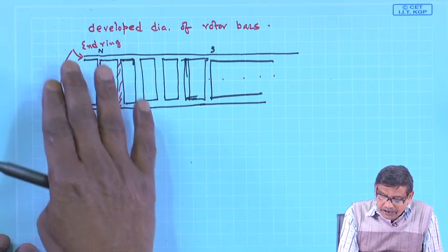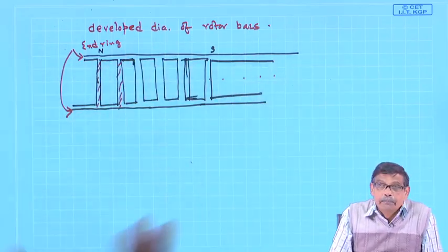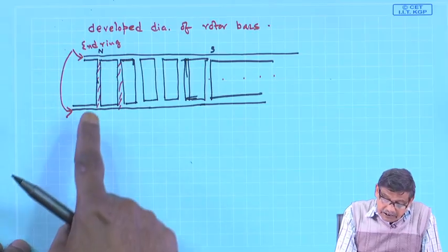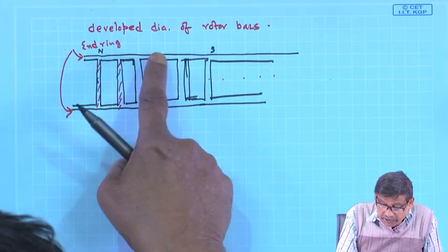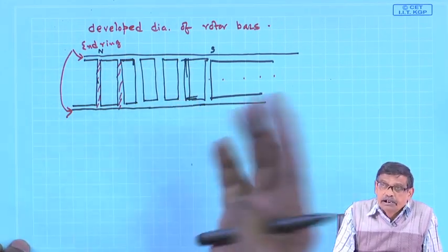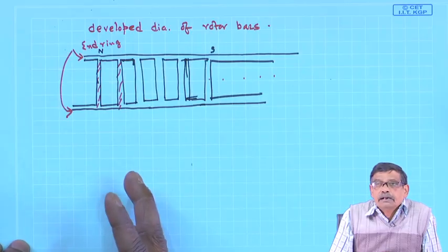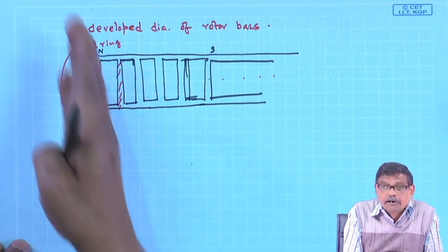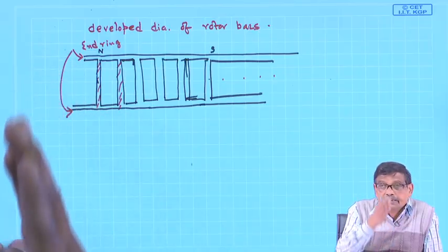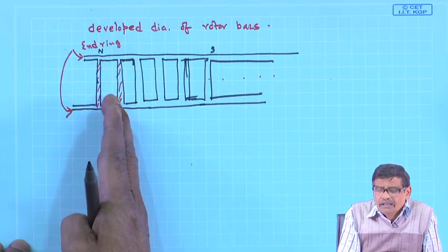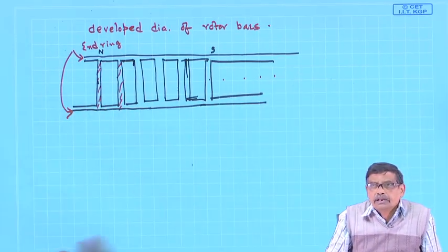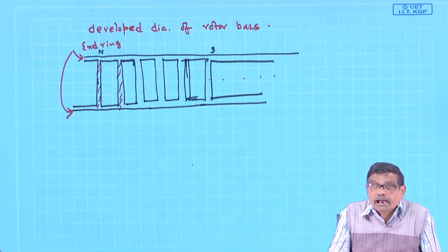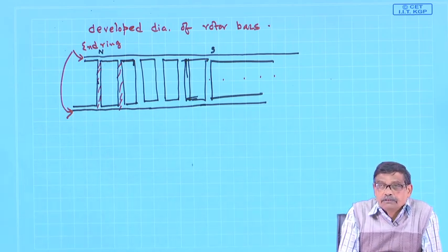That is the beauty. It is already shorted, but in a slip ring induction motor that is not possible, because the return conductor of a particular turn is already decided by me, and I have taken all the care that if one coil side is under the center of the north pole, generally the other coil side will be under the center of the south pole, and they have their own identity, a separate coil.